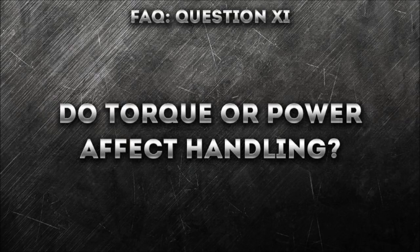Question number 11. Do torque or power affect handling? Power at the wheels affects handling through potential wheel spin. Tires give limited amounts of grip, which can be used for cornering or acceleration, or a mix of both in moderation. This is known as the circle of traction, where the length of the resulting acceleration vector made by combining the longitudinal and lateral acceleration is compared to the grip limit.